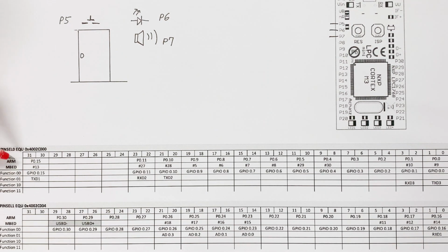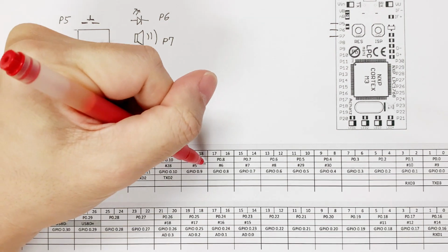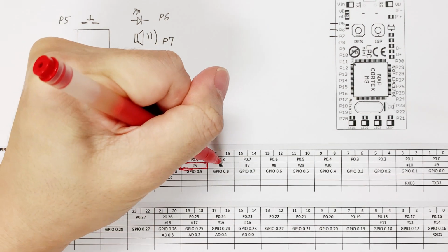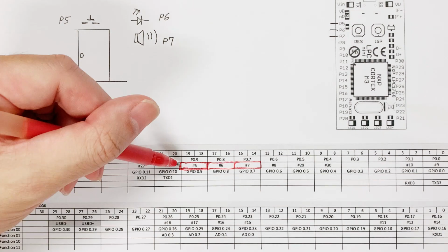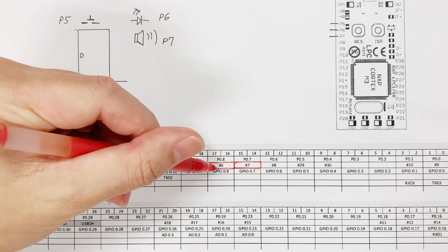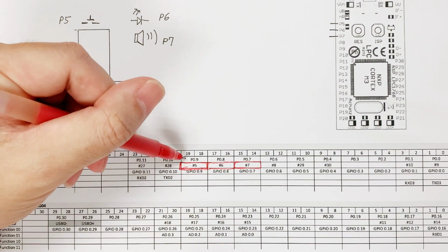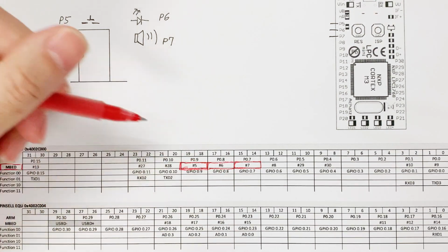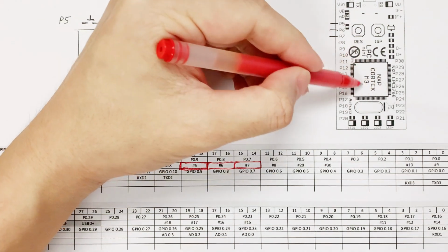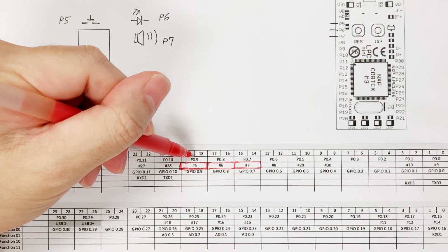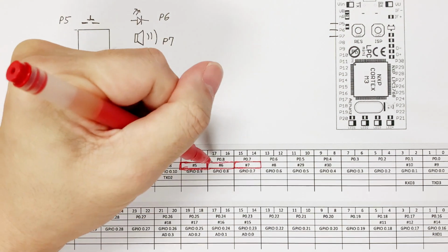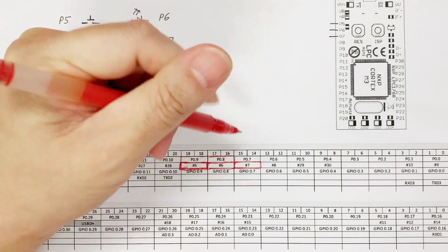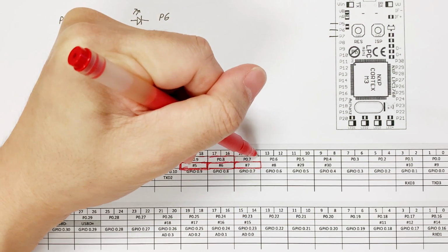Then, based on the template that we have, when we look at the MBED module, pin 5, pin 6, and pin 7 can be found there. After we have located pin 5, pin 6, and pin 7, we can determine what port number is being used in the ARM microprocessor itself. P5 is port 0.9, pin 6 is port 0.8, and pin 7 is port 0.7.